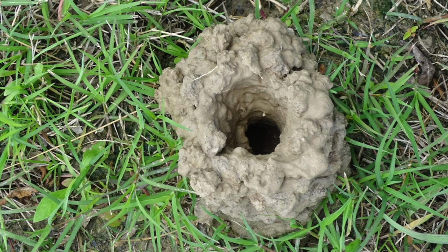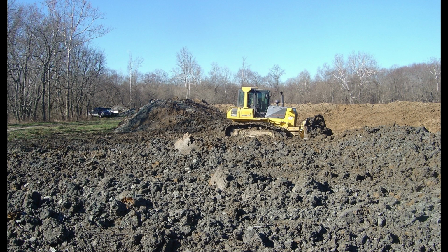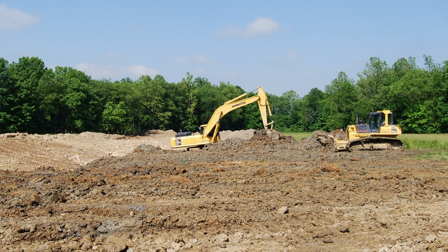Crayfish will not burrow in the completed groundwater dam because this clay is compacted and there's no groundwater present below the groundwater dam. The dozer is spreading the gravel removed from building the groundwater dam. Both the dozer and the excavator are spreading the topsoil that was saved over the clay in the finished groundwater dam and over the gravel that was spread.